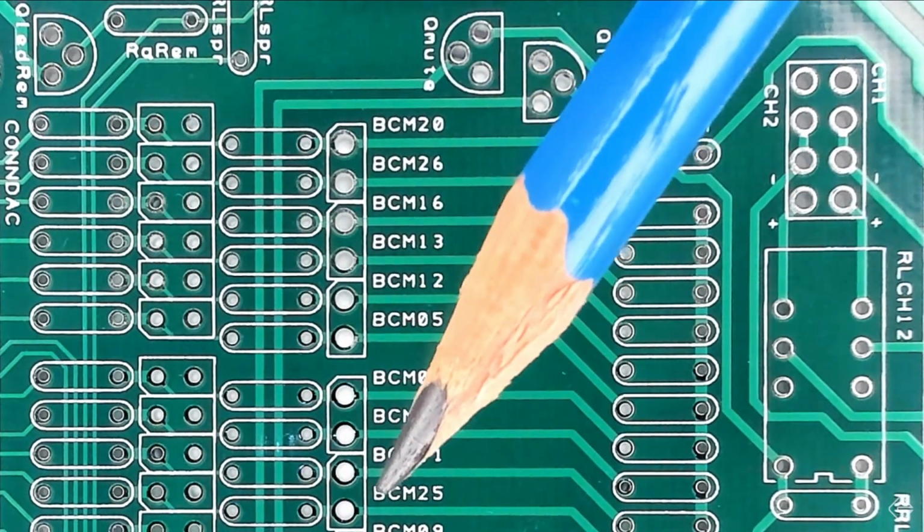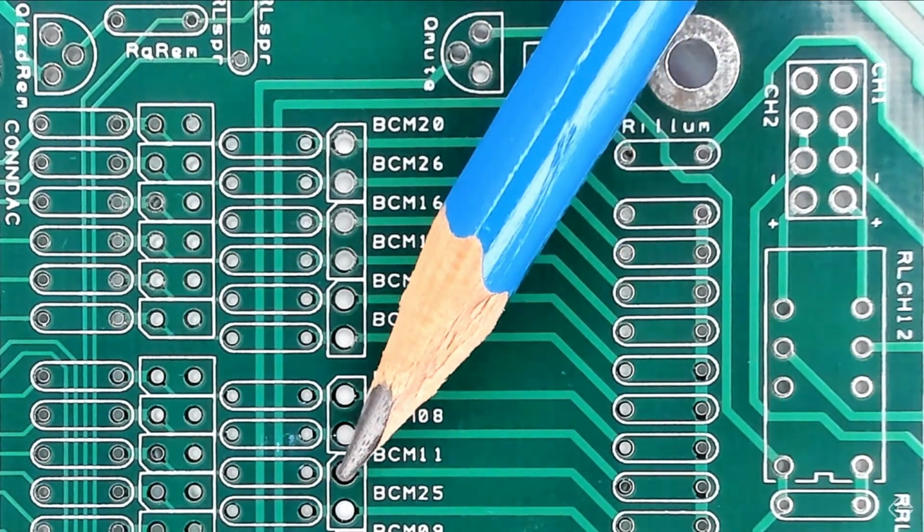If you need to cross it, you've got to make the trace go to the other side of the board so it can cross over. Each and every one of these through-hole pads has a hole that's drilled straight through. So every through-hole pad exists on every layer. And that's useful. That gives you a bridge that you can actually take a signal from the top layer and move it to the bottom layer.